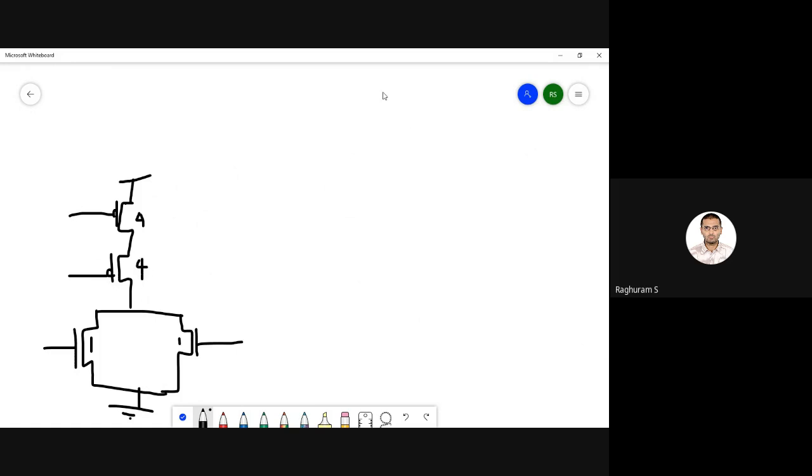Okay, so let us do the high skew over here. So it is a high skew. PMOS transistor network, I will not change any of the sizes. I'll put the same sizes. NMOS transistor, I will make the sizes of all the transistors half. Put the ground here.